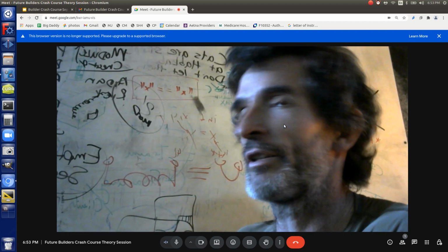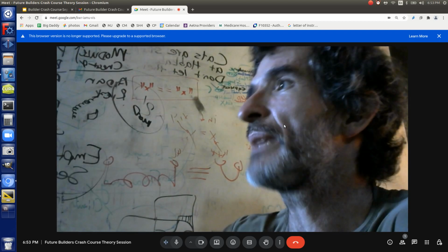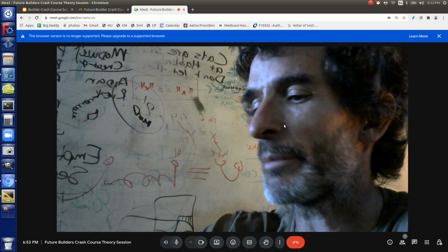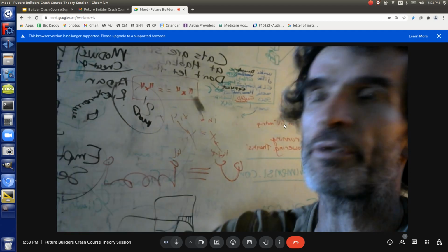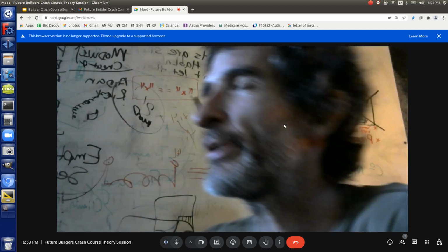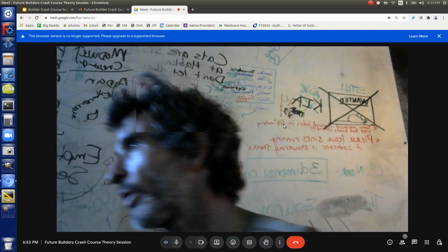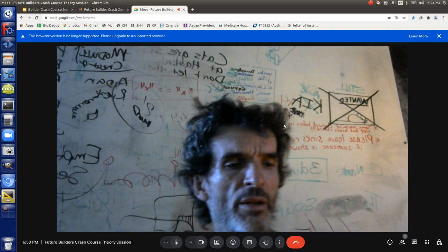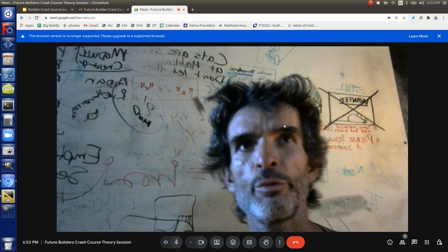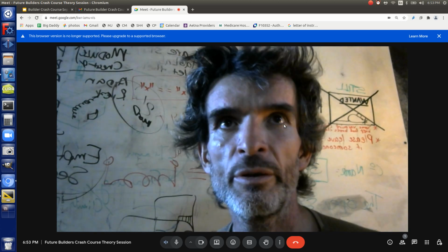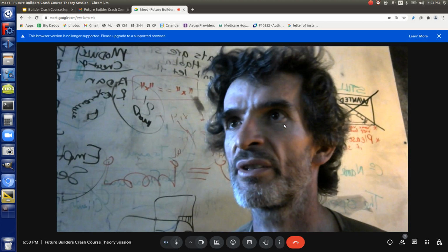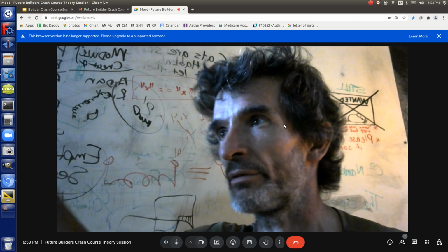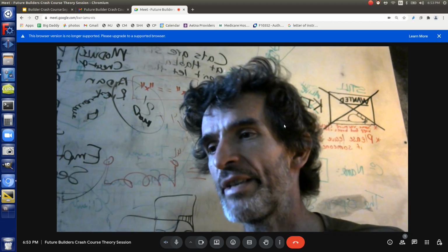So the big point is you've got to be able to. What I'm trying to talk about here is some basic concepts of first principle calculations. How do you actually start assessing all those values to know what's right or wrong? You've got to start with the 100,000 psi for steel, 1,000 for wood or less, concrete and plastic about 5,000. Okay, bam, there. You can get a lot out of that.